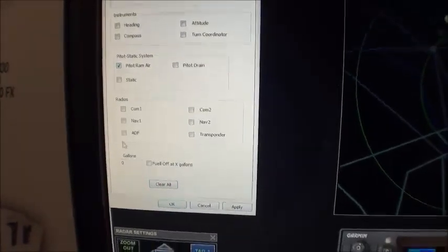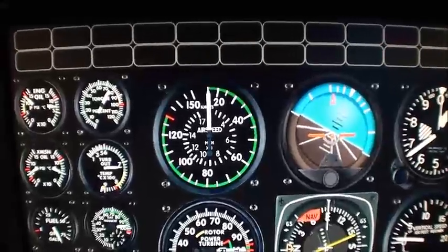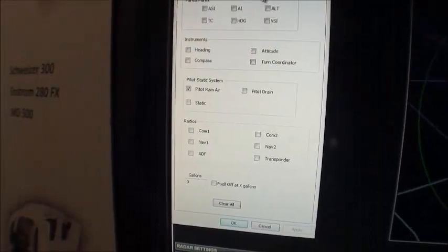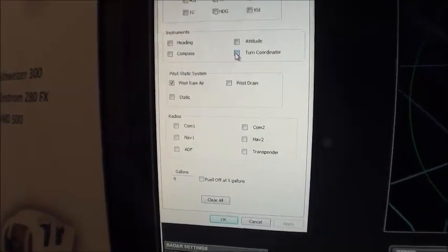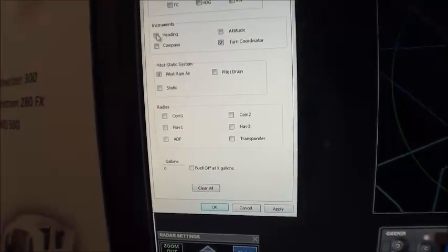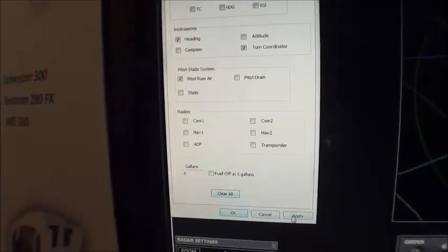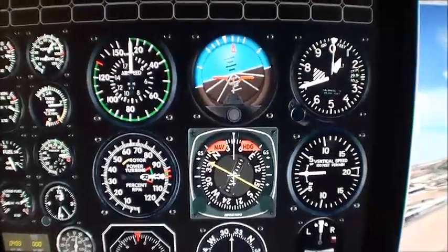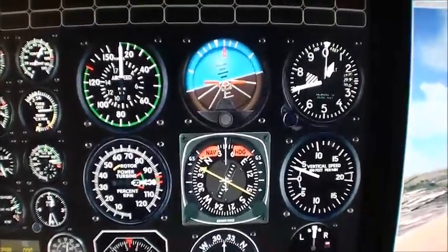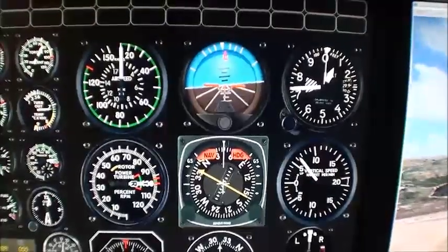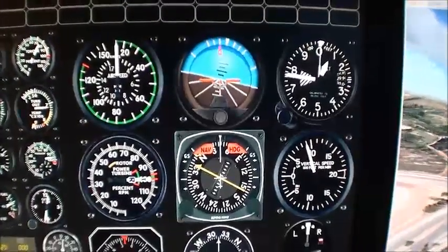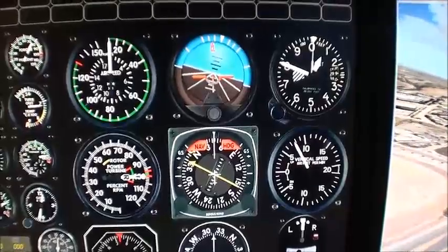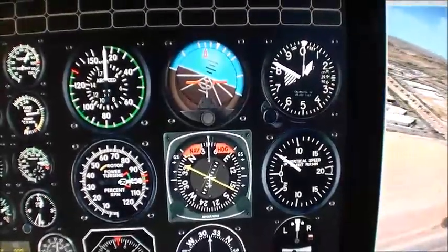the pitot system. And as we can see here, the airspeed went to 0. Okay, airspeed's to 0 here. We can fail turn coordinator, heading indicator. As you can see, now our heading has failed. Flag on the turn coordinator down here. See that? So these failures can be done real time. Flag here and also one down low.